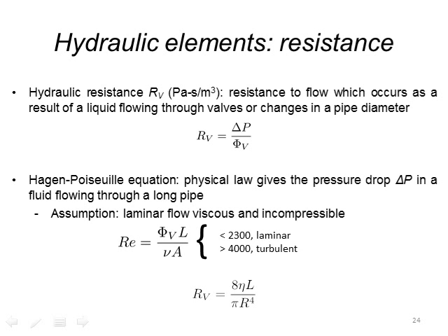And to be laminar, we have something called the Reynolds number that we have to calculate. To be laminar, this Reynolds number has to be lower than about 2,000, and then we can use these nice relationships similar to Ohm's law. If we have Reynolds numbers that are quite high, then the flow becomes turbulent and quite chaotic, and we can't use these well-behaved equations to estimate the hydraulic resistance.